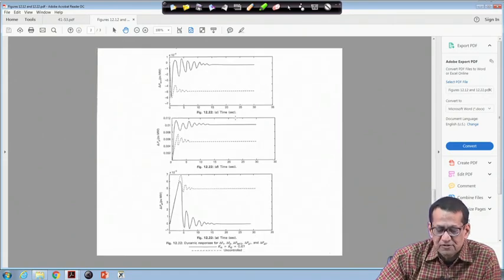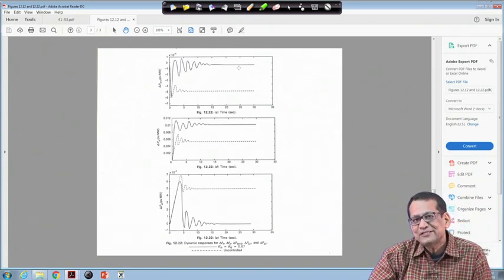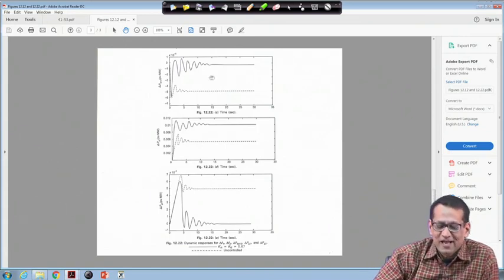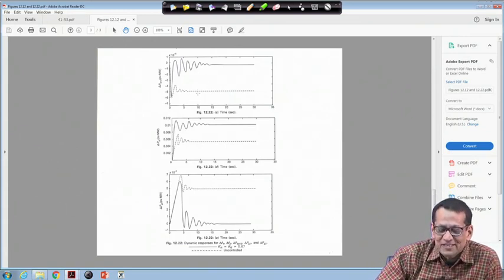And this is your tie line power. At steady state, the tie line power deviation is 0.005, minus 0.005, and when the integral controller is there, it is actually 0, right. So, if you give a 1% load disturbance, you will find that the tie line power is coming to minus 0.005. So, just half of delta PL, right.